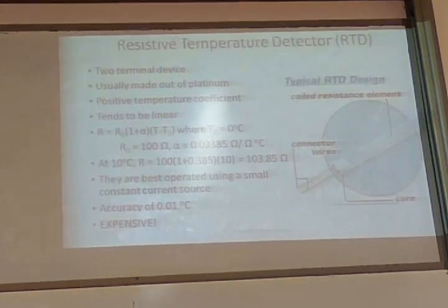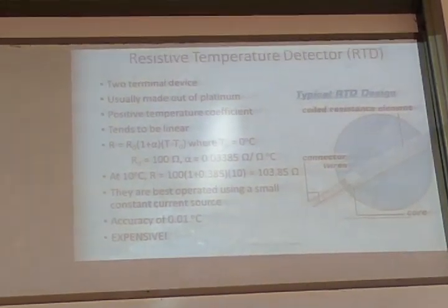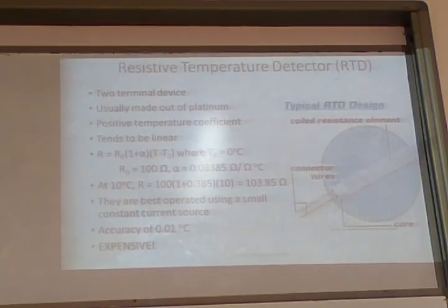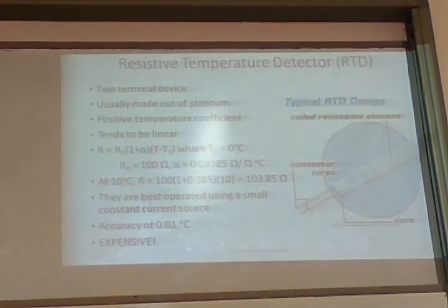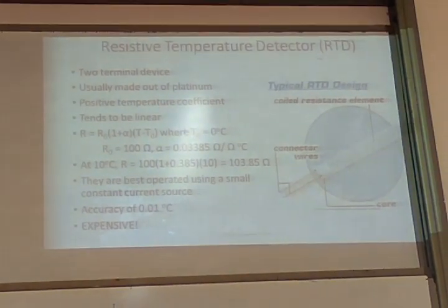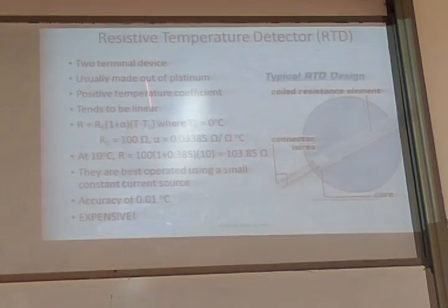Externally, in fact, I used to have this difficulty in the lab. We have both RTD and thermistor. We get mixed up. We don't know which is RTD and which is thermistor. So we use a multimeter and a matchbox, that technique, and then we find out. So more or less, it's all the same.